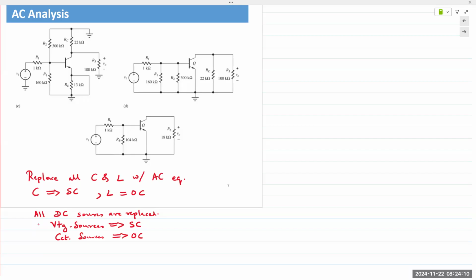Okay, so if we take a look at a circuit example, what do we see? Capacitors are shorted out. So AC input signal has a direct pathway into the base. Output can go directly to the load resistor. Now RE is canceled out because capacitor is a short circuit. And then the voltage source plus VCC is shorted out. So it's connected to ground, 0 volts.